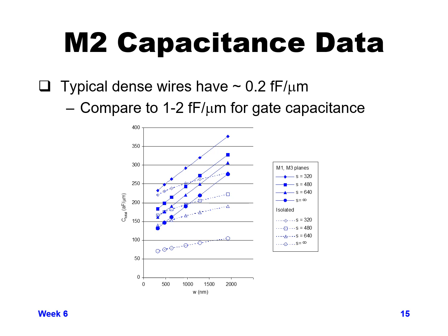So just to give you an idea of comparison, your metal 2 wire capacitance might be approximately 1/10 the value per unit micron of what your gate capacitance is. So it just gives you an idea of how metal capacitance compares to gate capacitance.